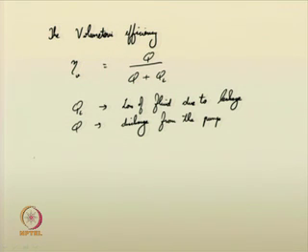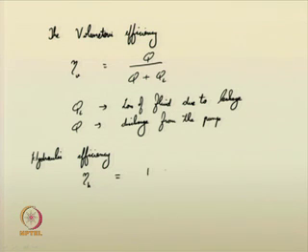Hydraulic efficiency. We can now correlate hydraulic efficiency, say by a factor eta h. This is nothing but 1 minus Hf by Hs. Can you recall these terms? Hf we suggested is the loss in the total energy head due to various things like friction. Hs is the energy supplied to the system, right. So, Hs is the energy head supplied to the system.